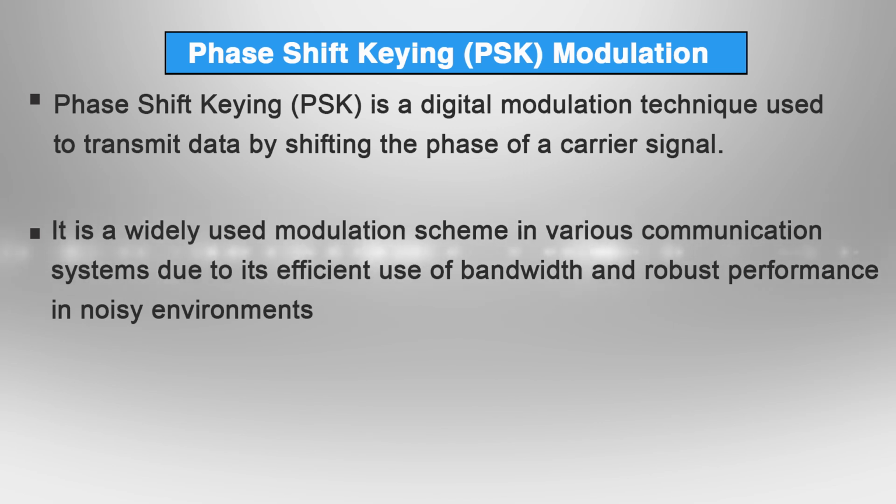Phase shift keying is one of the most efficient modulation techniques, as it is used for high data rate systems. In PSK, the phase of the sinusoidal carrier is changed according to the data bits to be transmitted. Also, a bipolar NRZ signal is used to represent the digital data coming from the digital sources. Whatever data we want to transmit should be represented in NRZ format.